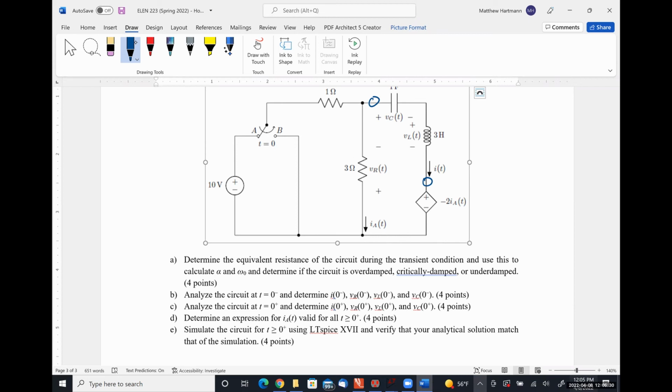There's no current flowing in anything. Oh, okay, so it just all goes 0. Yeah, so IA has to be 0. Because if you did KVL around this loop, you'd find that the voltage drop over the 1 ohm resistor plus the voltage drop over the 3 ohm resistor have to add up to 0, which is only true if no current's flowing. So that means IA is 0.